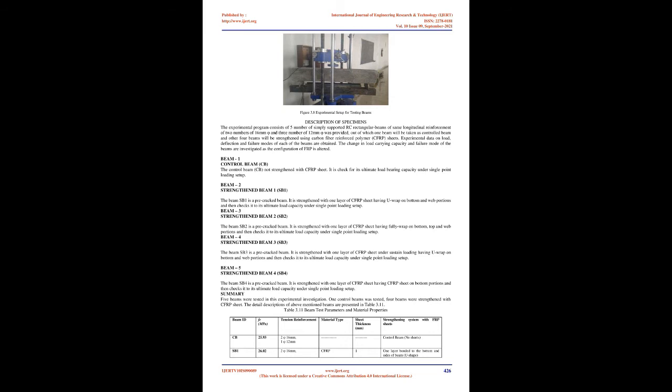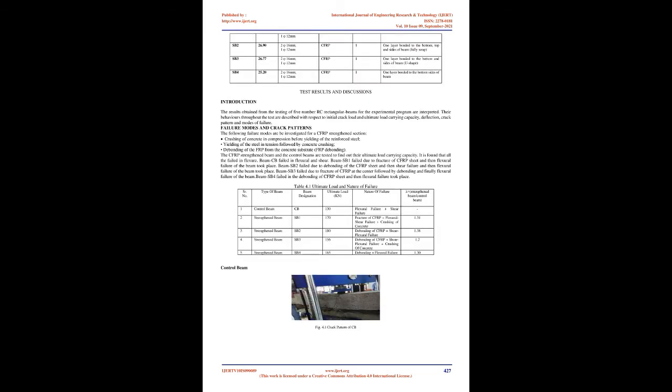The uniaxial compressive tests on the specimens, 150 × 150 × 150 mm concrete cubes, were performed, and the average concrete compressive strength at 28 days for each beam is shown in Table 3.2. Water. Water fit for drinking is generally considered good for making the concrete. Water should be free from acids, alkalis, oils, vegetables, or other organic impurities.